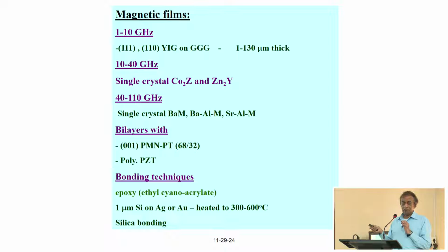I discussed this some time ago, where you have two halogen lamps, you heat a polycrystalline seed to about 1700 degrees Celsius, then there is a small sample of single crystal seed. So, once you start cooling the polycrystalline seed at a very slow rate, like 1 degree per minute, the cooling should be very slow for it to grow the single crystal.